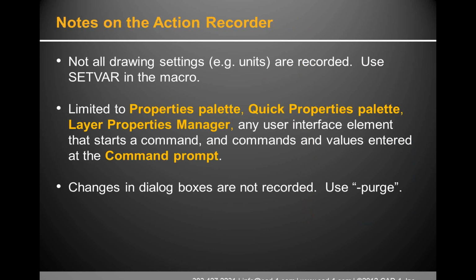And will you be showing where that gets saved to? Yeah, we can actually show, and I'll show you. I like to show this a lot when we talk about path and pathing within AutoCAD. Usually I'll show on screen where we can determine where things are getting saved, things like where are my autosave files getting saved. It's always handy to know how to detect that, how to find those paths on your own. So I'll show you that as well, where the roaming profile gets saved.